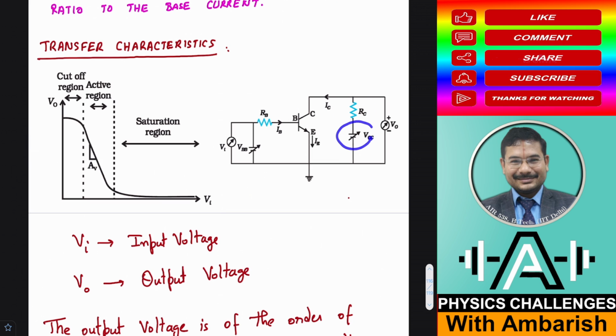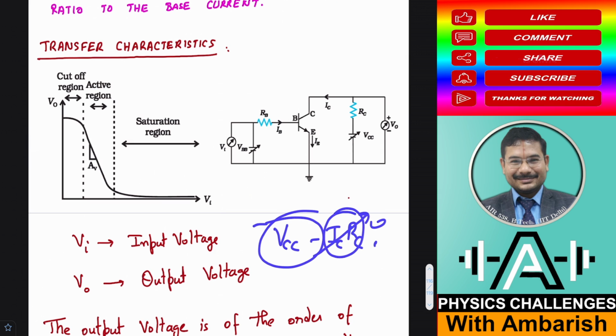So you are getting the full value of VCC. Why? Because the output voltage is actually VCC minus ICRC. So when IC is 0, you are getting the entire VCC as the output voltage. So when the input voltage is very small, the transistor is in the cutoff region, and you are getting a very high value of the output voltage.